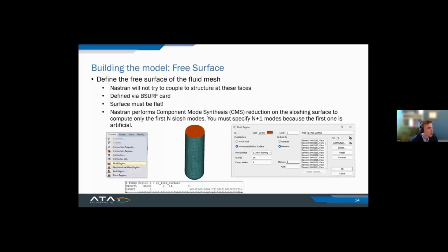So I guess that depends on how much your gravity vector changes, right? Typically on a launch vehicle, your acceleration is never perfectly along the longitudinal axis. You might fly at some small angle of attack, maybe 4-ish degrees. Typically that's totally appropriate. Once you get to some larger angle than that, yeah, you might have to remesh your fluid mesh to account for that actual shift.